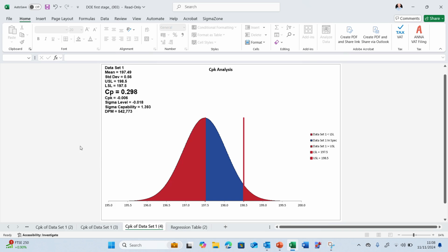So although we could run faster, we will bang an enormous defect rate through the CpK2 according to our model. Now, you can make a business decision based on this. It's up to you which one you think's the best. To be honest, it looks like being defect free and running at 1 minute cycle time is going to be the best choice, because if you've got a defect rate as heavy as that, you're going to have to run the machine 3 times faster to keep up.